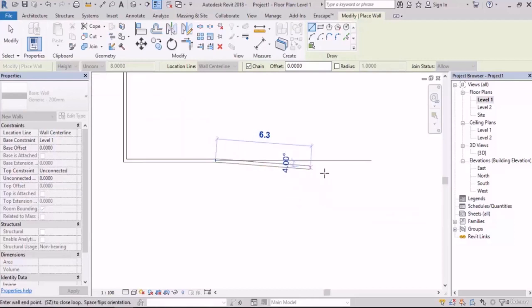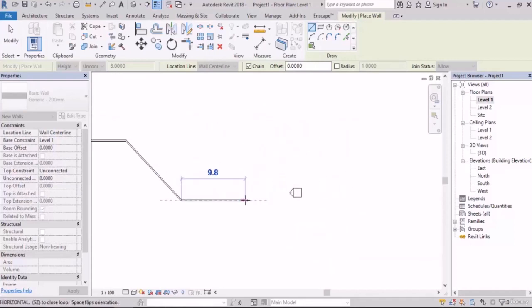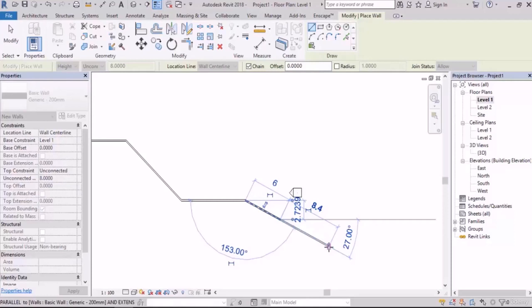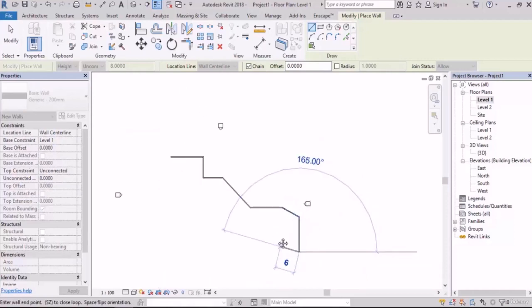In Revit, we have no special place for you to enter that angle. So if I want to bring my angle down, you will hold your mouse and drag it down to change your angle. And after that, I will write its length, for example, 12. Let's do it one more time. For example, with 27 degrees down, I get it down, and when I see 27, I stop. I let my mouse go and I will write down the length. Just like this.